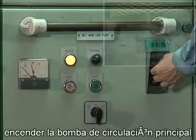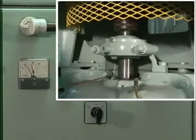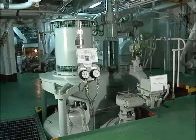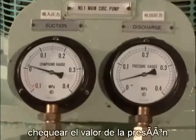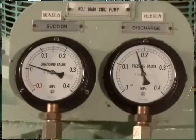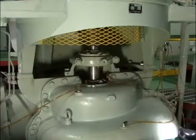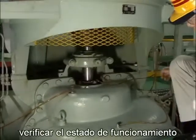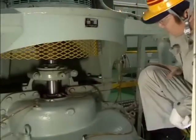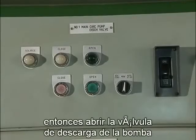Start the main circulating pump and check electric current value. Check pressure value. Confirm the state of running. Then open the pump discharge valve.